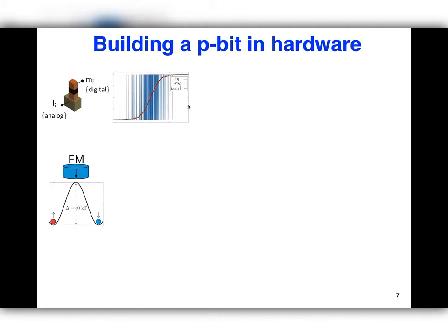If you remember the freshman physics of magnets, a magnet is really this object that can be in one of these two states, red or blue, or up or down, north or south, that are separated by an energy barrier, something of the order of 40 or 60 kT. Now, if you leave a magnet in one of these states in the presence of thermal noise, which has energy equivalents of around a kT or so, it turns out the magnet tends to stay in one of these energy wells, okay? And the way to understand how this noise behaves is that tau is the retention time, or the time it takes for the magnet to stay in its current state.